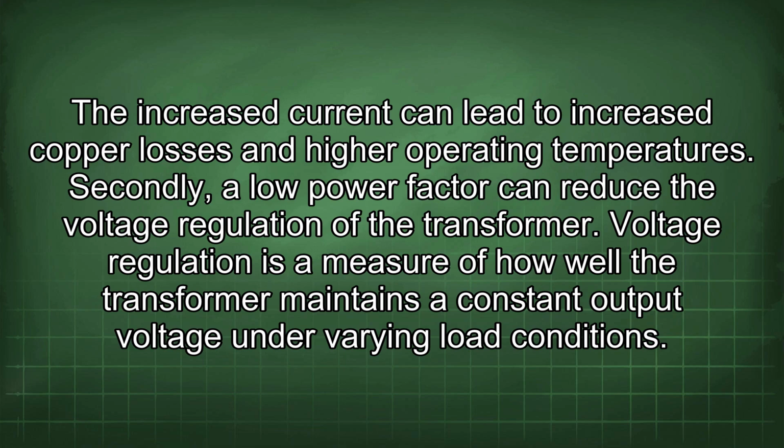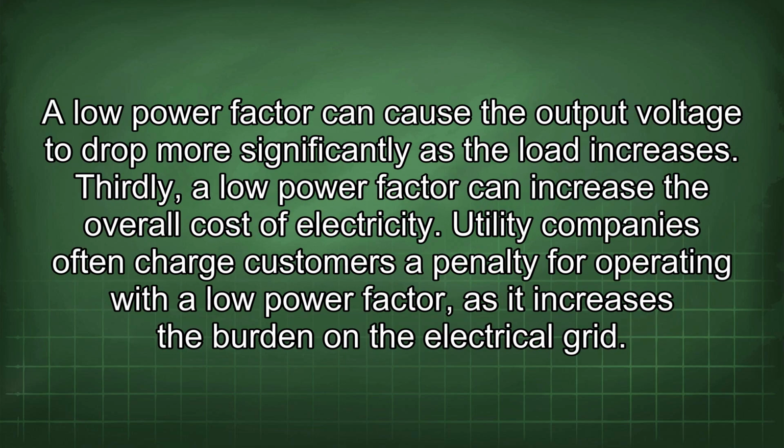Secondly, a low power factor can reduce the voltage regulation of the transformer. Voltage regulation is a measure of how well the transformer maintains a constant output voltage under varying load conditions. A low power factor can cause the output voltage to drop more significantly as the load increases. Thirdly, a low power factor can increase the overall cost of electricity.